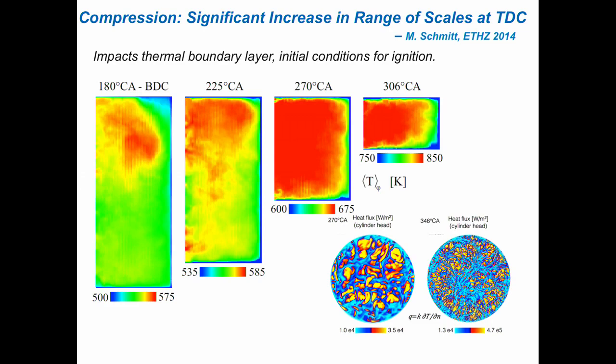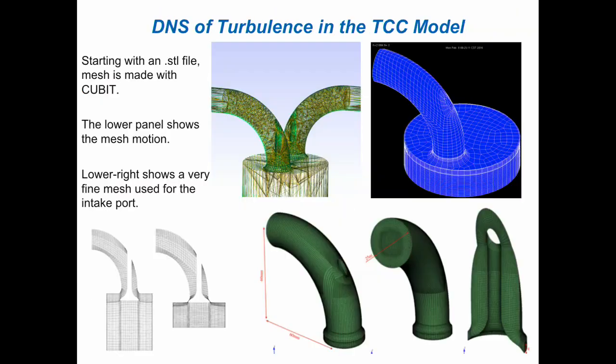One of the more interesting things is that as you get up to top dead center, the flow gets more and more turbulent. Why is that? Well, the density goes up. That's the short answer. The density goes up, and the result is a higher Reynolds number. It has a rather deep influence on the heat transfer around the walls and the top and the bottom of the cylinder. And the guy who has done this calculation has already filed some patents based on his insight from these calculations.